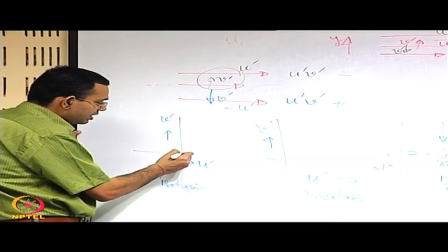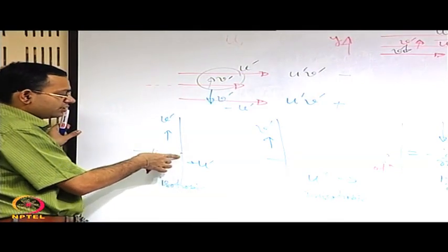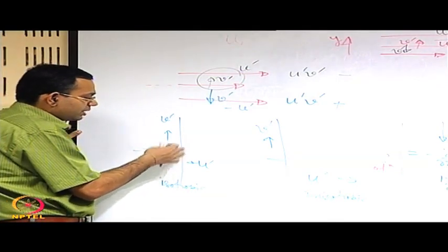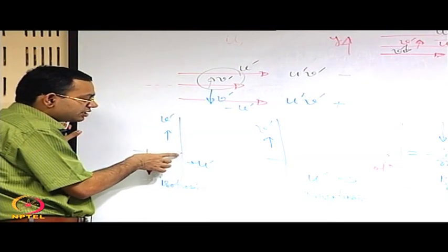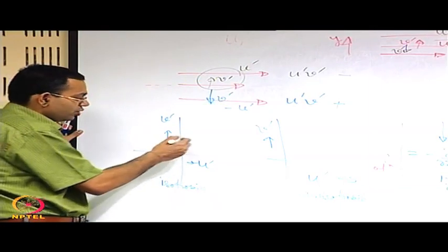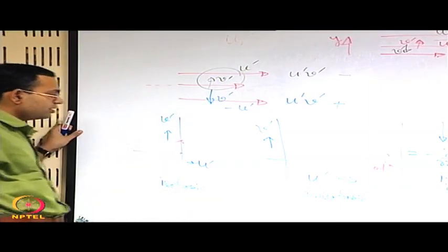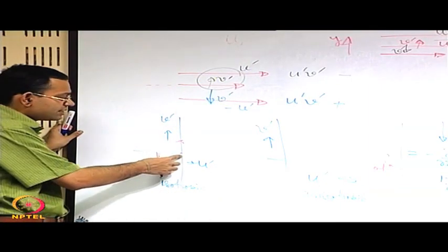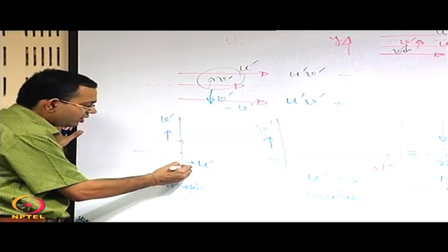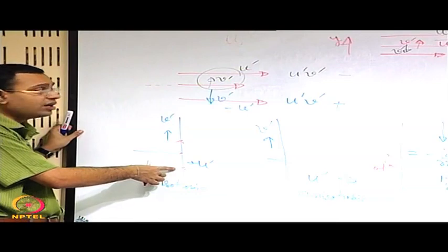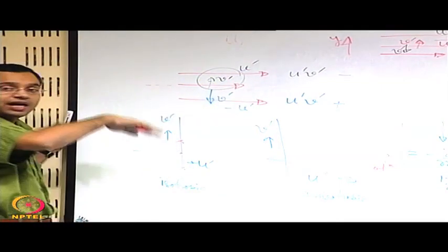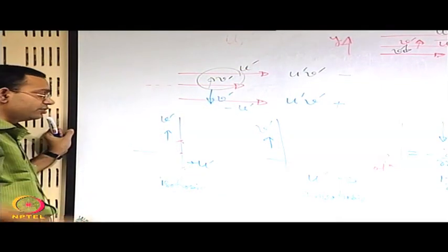So, when you have isotropic, let us consider one case where you have a deviation with, say, u prime equal to 0. If you have a case with v prime as some positive quantity, you also have an equally probable case with v prime as negative of the same, because the average of u prime v prime taken over all possible values should be 0.